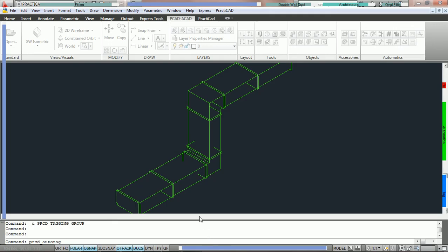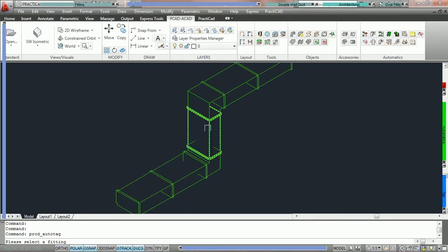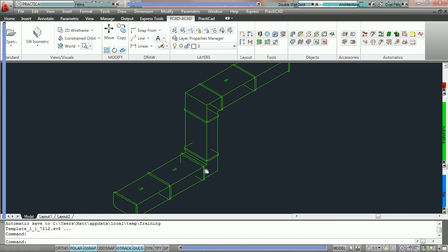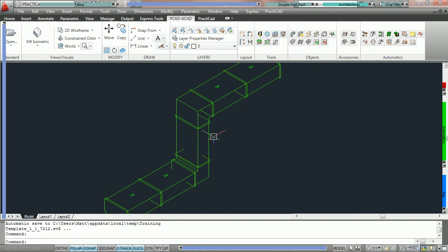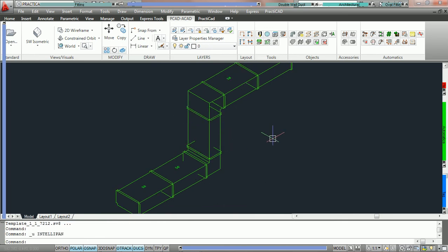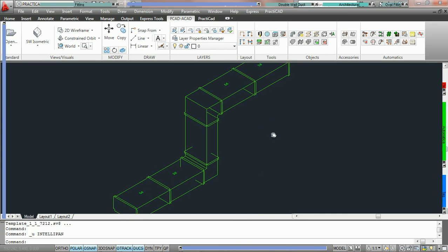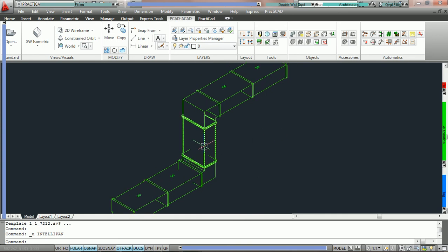We're going to press OK, and here we've got an elevated view with one fitting that's going up in a rising setting. We're going to click and notice that all the ducts get length tags, but this piece doesn't, because the parameters for the length tag that we've chosen in terms of direction interval do not apply to this fitting. And since we had use default place unchecked, it did not place a tag here.